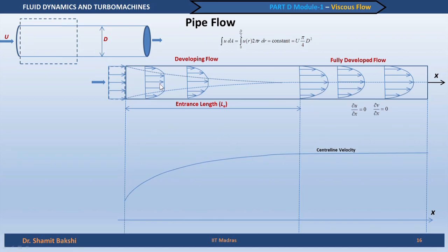So, we can actually apply Bernoulli's equation there. It is an inviscid flow, and let us say this pipe is straight like what is shown here. So, the height of the pipe from the reference frame fixed to the ground is the same at the initial and final portions. If we apply Bernoulli's equation, it means if the velocity increases the pressure will drop. So, the pressure drops in this region very significantly because the velocity increases.